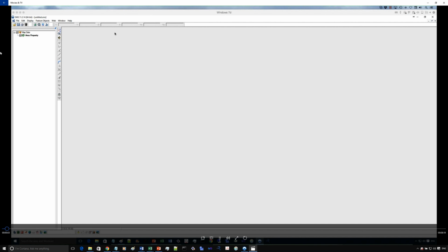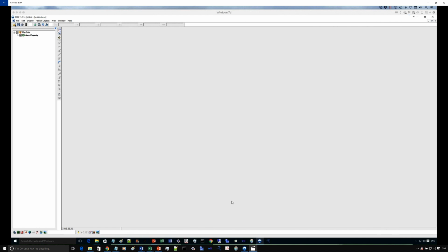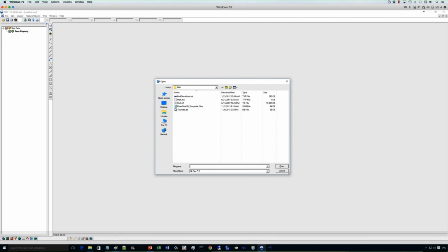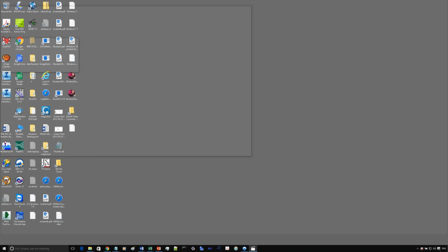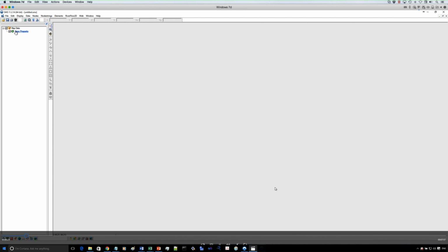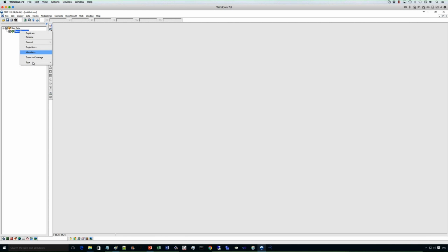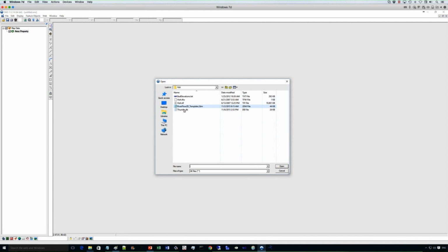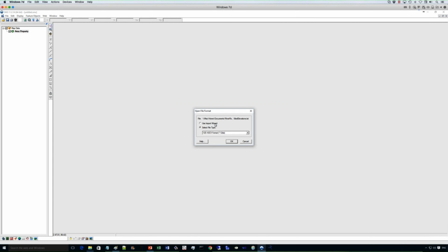Okay, so the first thing we do, we open the SMS program, and we locate the RiverFlow2D template, which is the one that creates the whole RiverFlow2D system within the SMS program. So we go ahead and open that. This area property is the conceptual coverage where we are going to enter the domain extent. We'll define that as a type model generic 2D mesh. And then we import the elevation data set. This file here is XYZ data. We use the import wizard.